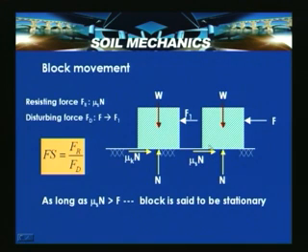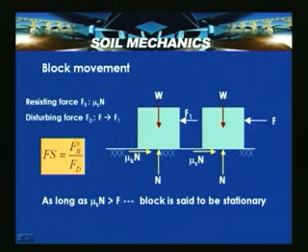So, here the resisting force is the frictional force which is offered by the particular material. So, it depends upon the type of the interface this block has. Under static conditions it is mu Sn, but once it is under movement, say F1 is causing the movement to the block, then mu S changes to mu K, that is kinetic friction. In this case, a factor of safety can be defined, a term which is used for knowing whether the slope is stable or not, or on the verge of failure. Using the simple analogy, the factor of safety is equal to Fr by Fd, where Fr is the resisting force and Fd is the driving force. In this case the driving force is F and the resisting force is mu Sn.